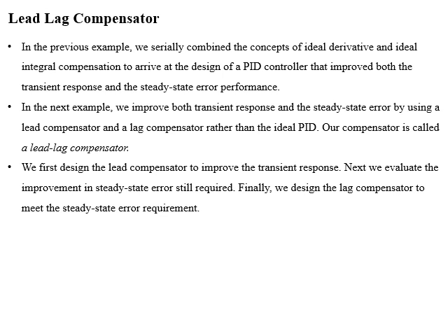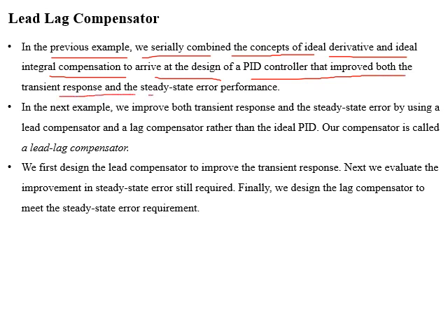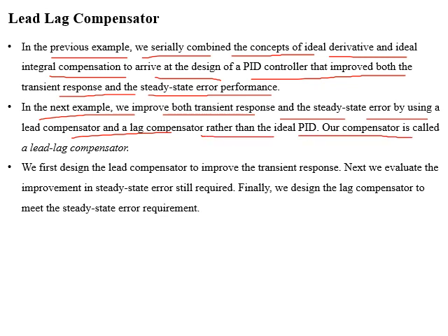Dear students, in previous example, we serially combined the concept of ideal derivative and ideal integral compensation to reach the design of PID controller, which improves both transient response and steady-state error specifications. Now we will study how to improve both transient response and steady-state error by using a lead compensator and lag compensator rather than the ideal PID. Our compensator is known as lead lag compensator.